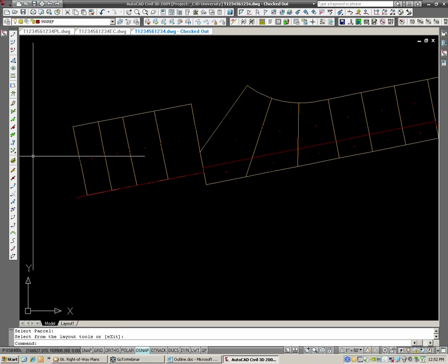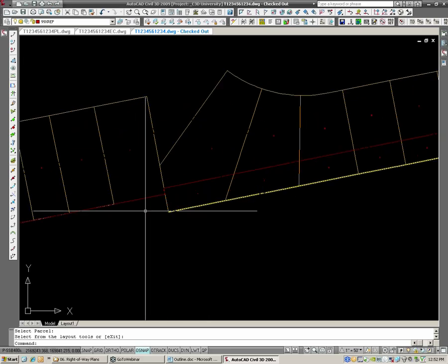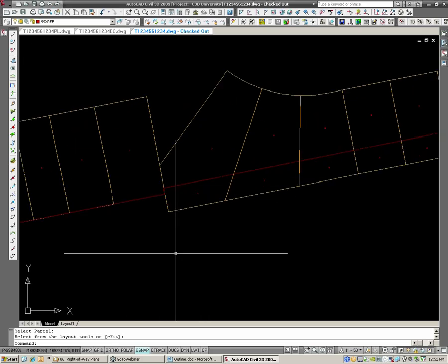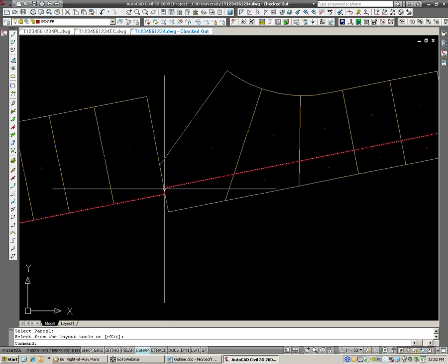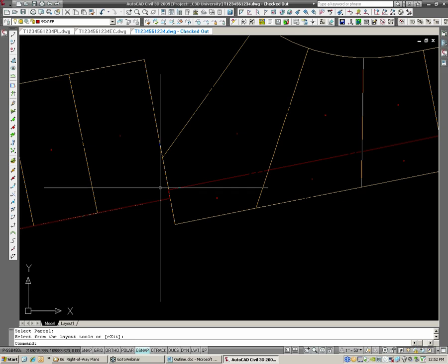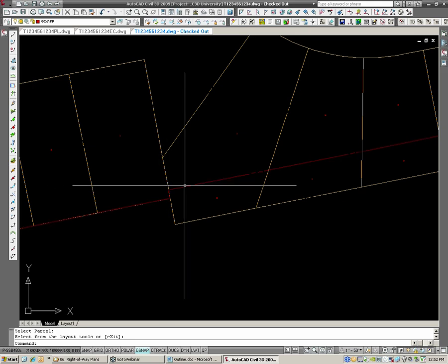There's another piece on right-of-way plans that seems like a real pain, which is the summary of project coordinates, or the summary of right-of-way coordinates, where you list the right-of-way, and at every point where there's a bend or break, it has a station and offset from the center line, what that is, if it's just a break, a PC, a PT, the northing and easting coordinates of that, and then the bearing along that line.